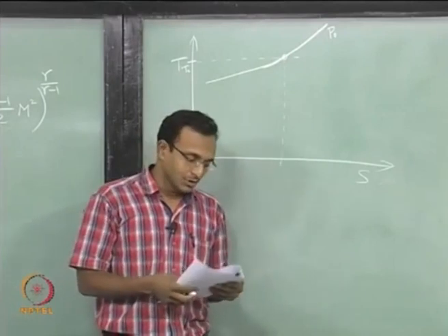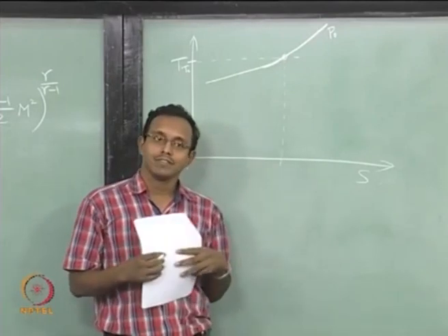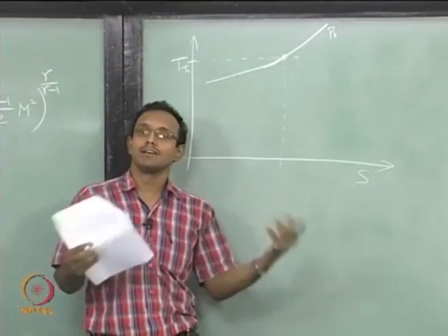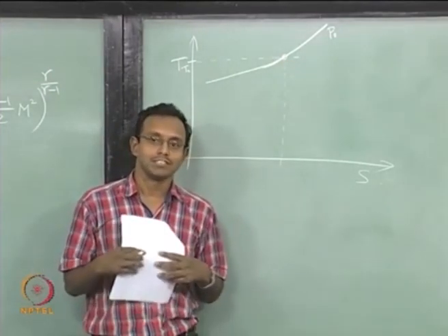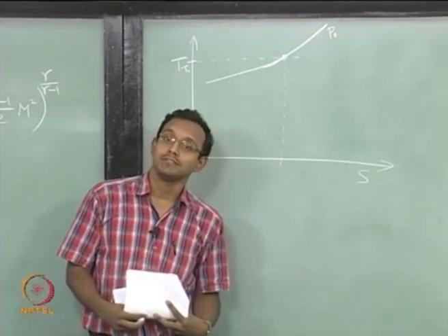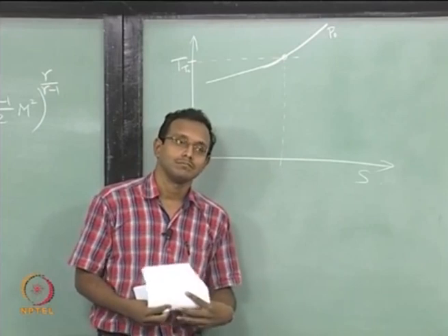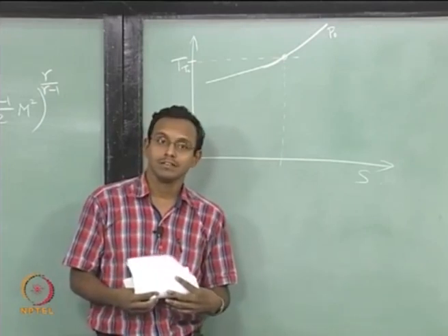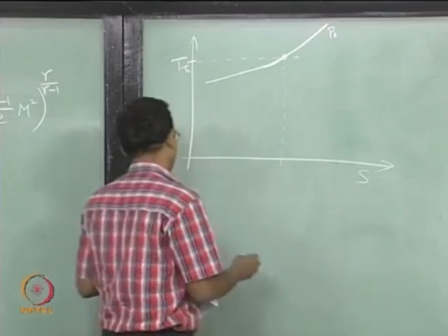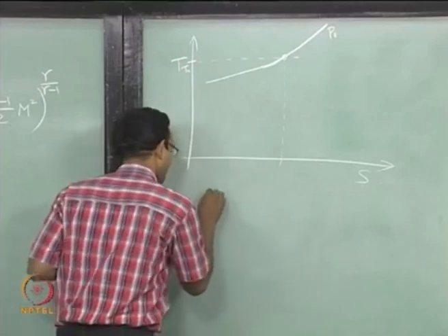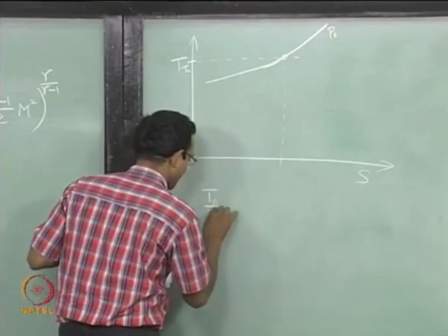So let us say I am going to accelerate this fluid to some subsonic condition, some subsonic velocity. What will happen to my pressure? It will decrease. Why? What happens to temperature? Easier to look at is temperature.